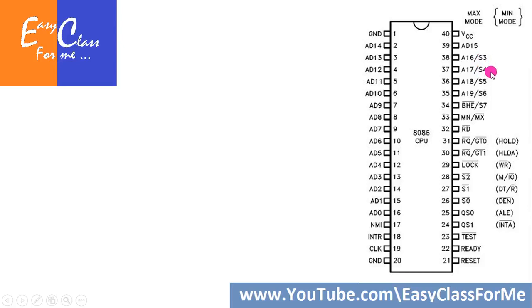Now in the architecture we have seen that when we had an externally interfaced memory of 1 megabyte, that memory contained 4 different segments of 64 kilobytes each. They were called the code segment, stack segment, extra segment and data segment. So when this microprocessor is accessing that memory, how will it indicate to the external world that it wants to access one particular segment of memory? For that purpose these S3 and S4 bits are used, and the way in which this processor indicates to the external memory that it wants to access your code segment or your data segment is shown here.